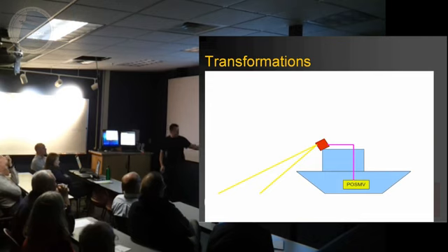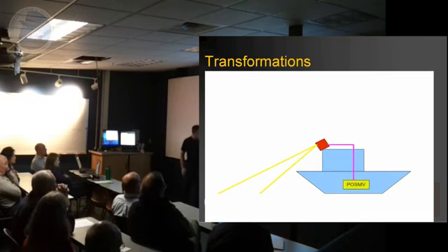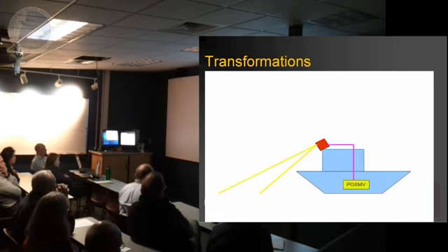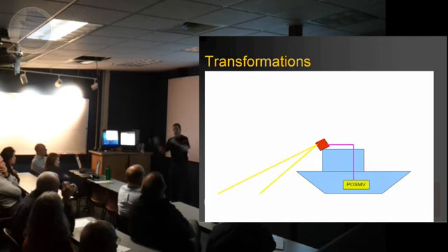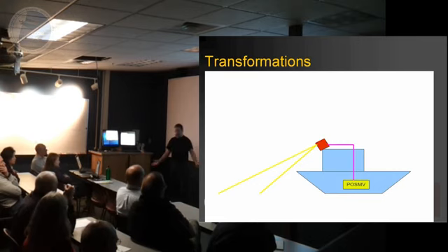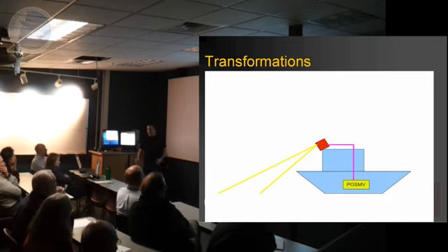So if I go back here, our pixels, which are captured at the camera, which represent these little patches of ice, get perspectively transformed here, apply a rotation and translation to know where we are relative to the ship. The GPS tells us where we are relative to the world. Therefore, that little patch that I started with, we now know where it would go on a map. So that's how the whole system gets us from a picture to a map.